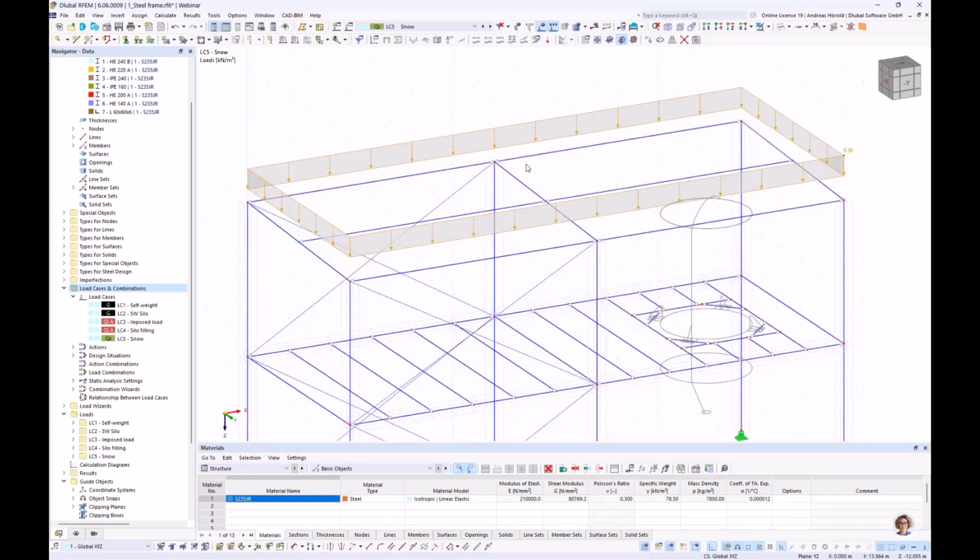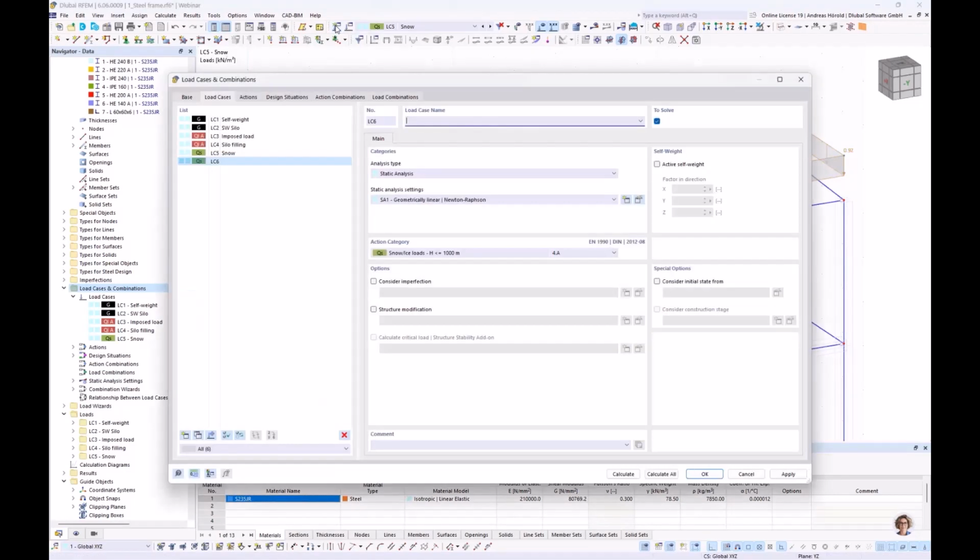So then we create the next load cases. I go to new load case. We would like to consider 4 wind load cases, the wind in plus X direction and the wind in plus Y direction, with wind pressure and wind suction.